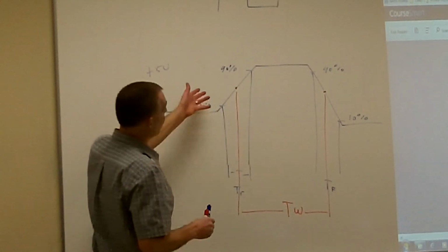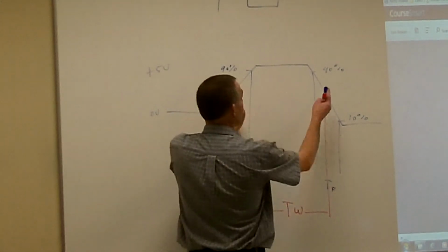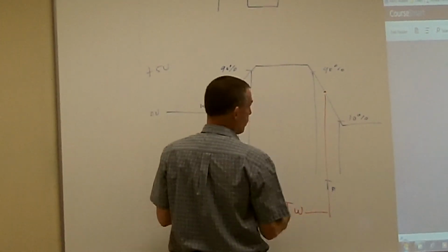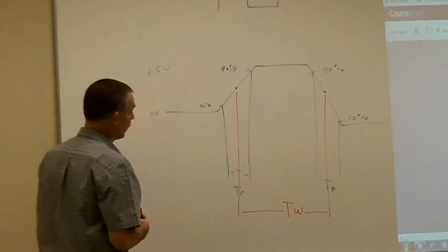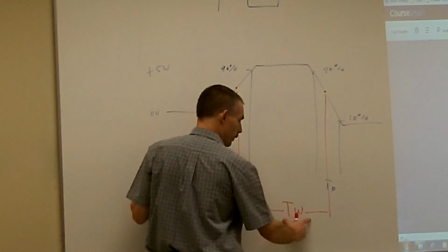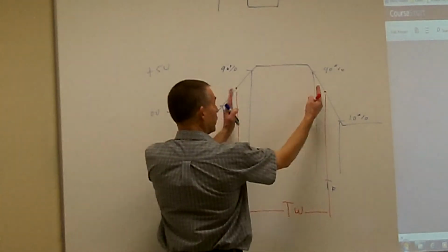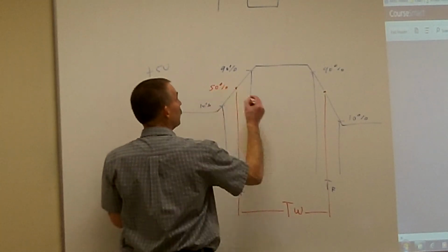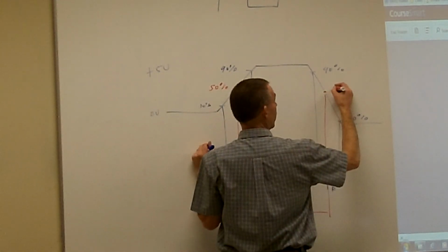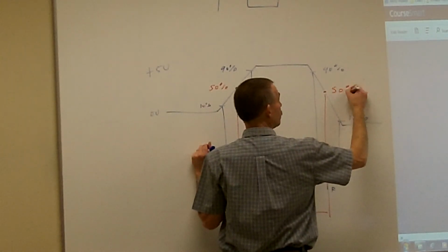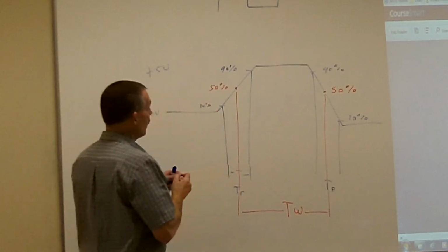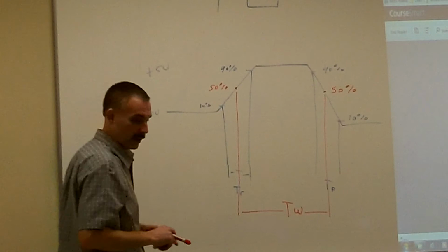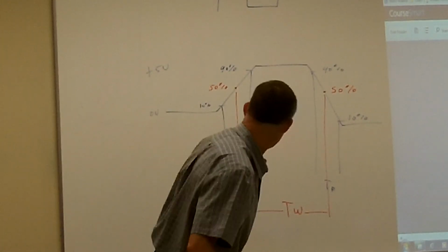We're going to have a negative 1 pulse, or a positive 1 pulse. It doesn't matter what it is. Calculate everything else the same way. So this is actually our pulse width, or our time width, of what the actual pulse is. That's at 50% of our waveform, between where the rise time and the fall time are. And this is where those cursors come in handy. When I was talking about the cursors on the oscilloscope,